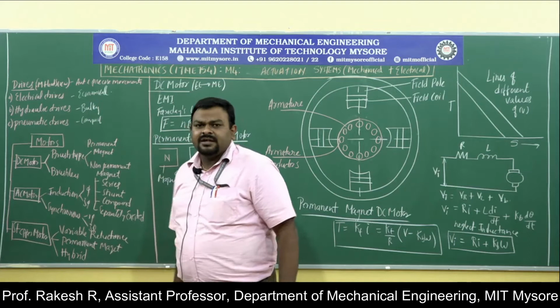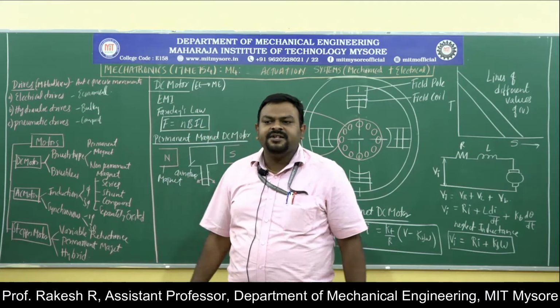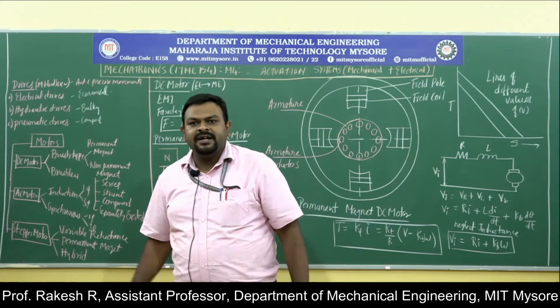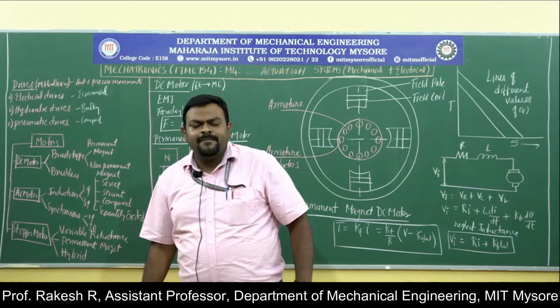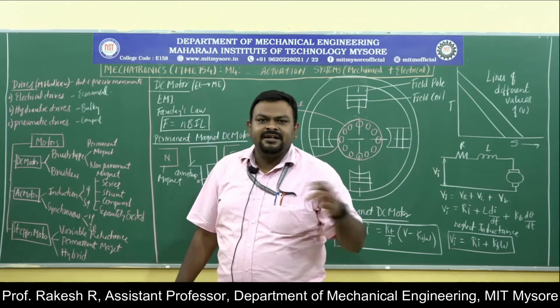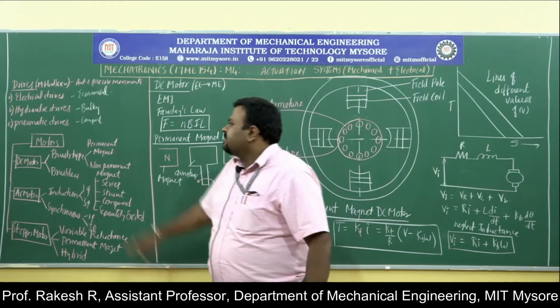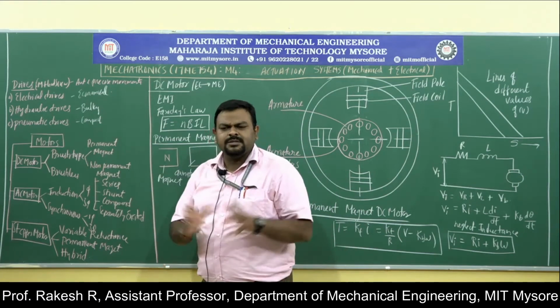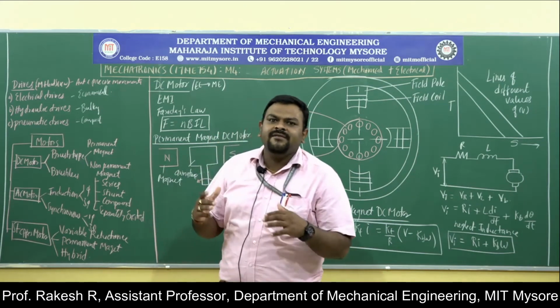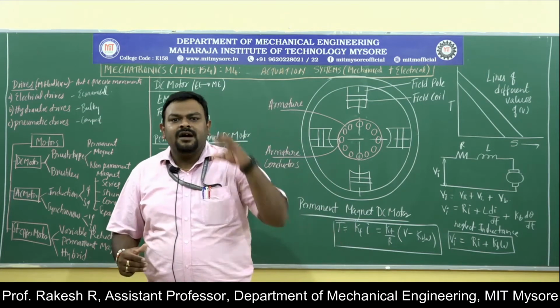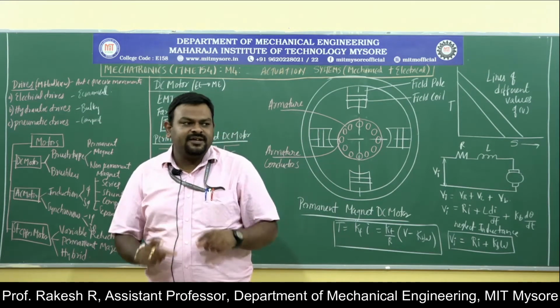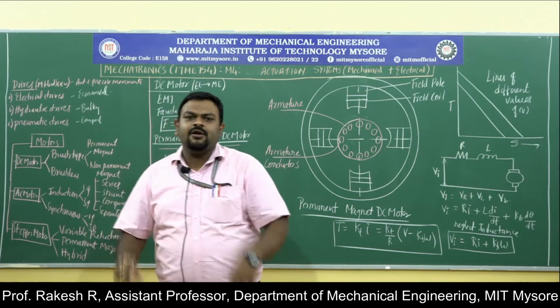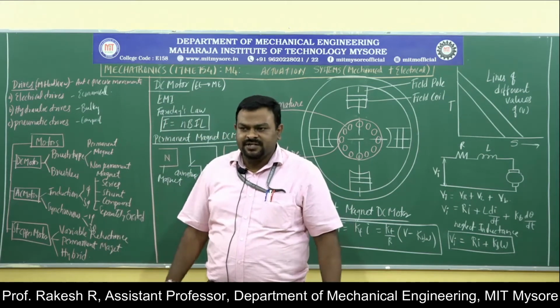If you are using an electrical drive, it is economical in nature, it is very easy to incorporate, and establishing a relationship between the electrical system and electrical devices is almost easier. Then hydraulic drives are somewhat bulky because they will have an inbuilt pump along with a reservoir, non-return valve, pressure relief valve, like that. The components will be more in the case of hydraulic systems.